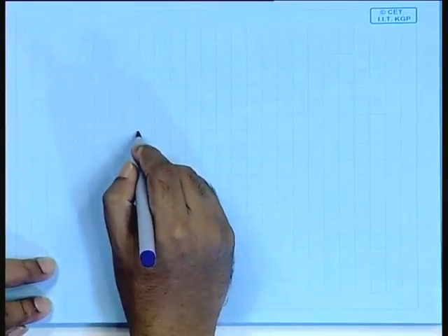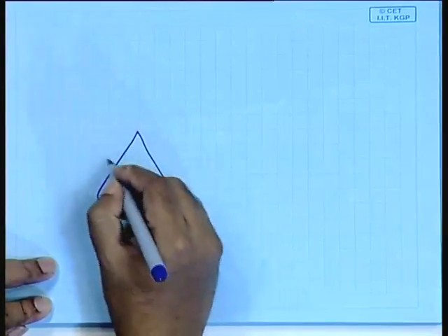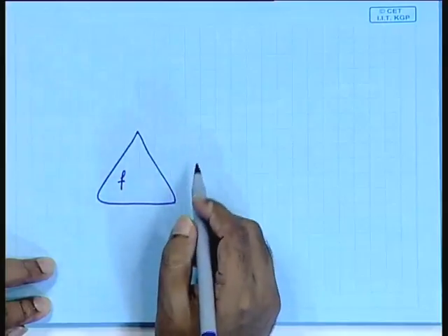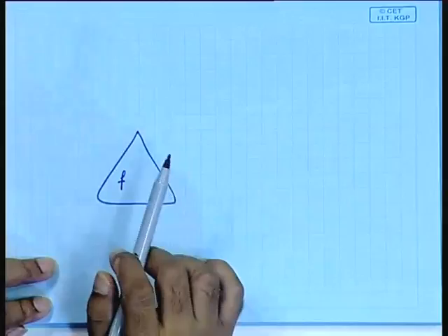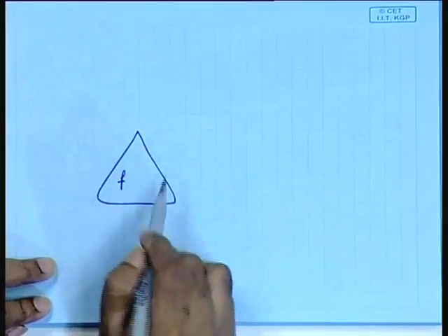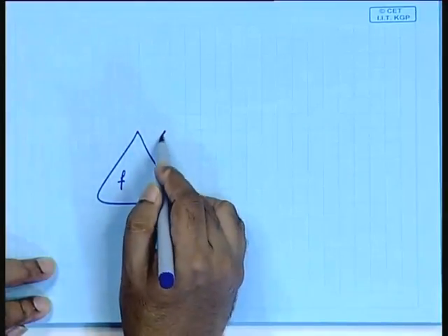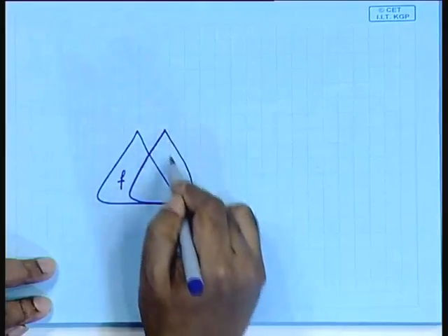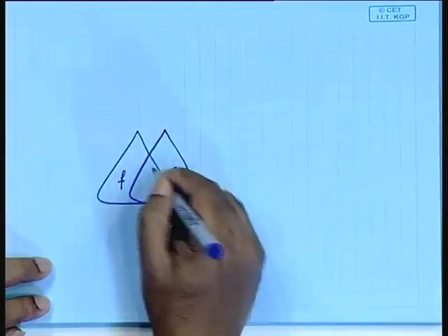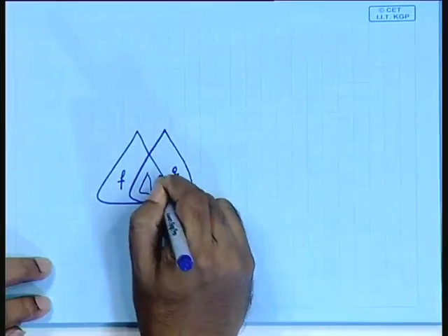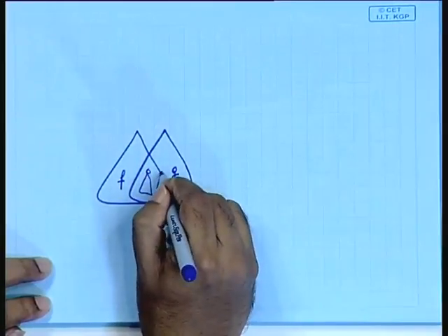So, in that structure it is going to create the BDD for f. When you create the BDD for g, if that function uses some sub functions of f, then it will use that. So, the BDD for g is not necessarily a completely separate thing. It might use certain common sub functions represented by these nodes.